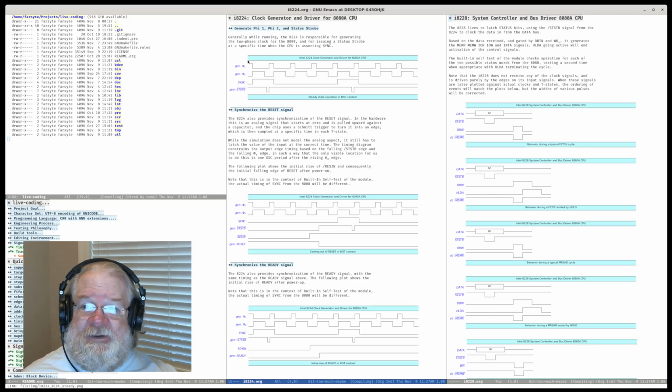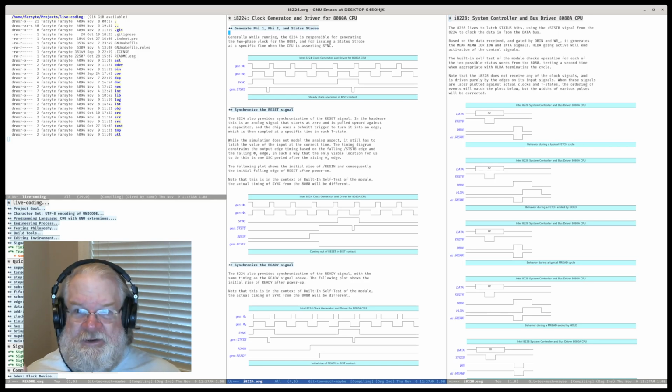What we actually simulate is that internally there is a clock signal that we're raising up and down and up and down. The fundamental unit of computation in this simulation is an edge. You have a data structure that says, I am going to represent what's going on in a signal, so you can subscribe to this and get called when there's a rising edge or a falling edge. And we've got one of these called clock.